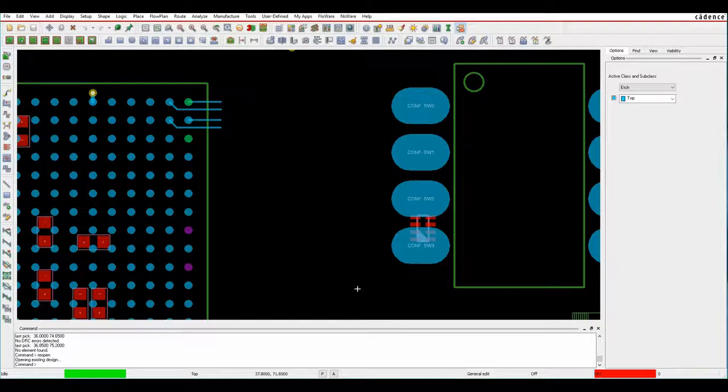Okay, this how-to video is going to talk about return path vias and adding return path vias for a differential pair. Many users want to add return path vias when they're adding a via pair on a differential pair, to improve the signal integrity and performance of the differential pair. I currently need an Allegro PCB Designer with a high-speed license to be able to do this.